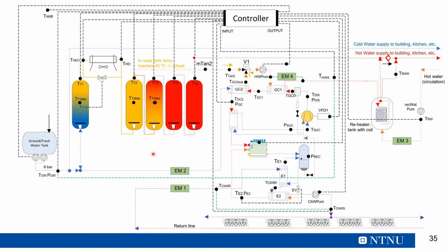And the return water which will be available from the hotel premises will be reheated. It will not go directly towards mixing with the fresh water, but it is reheated with the hot water we already have and goes back to the system. So this is the effective way of using it, and this is how we are designing the controlling strategy of the unit.